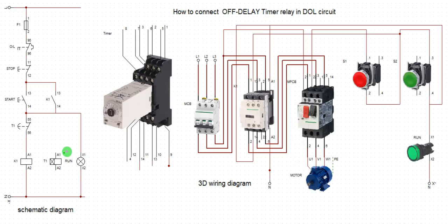All right, just pay attention, please. This is the coil, this is the contact. So I feed the coil through my latching branch and also feed the negative, positive, neutral from here. Within my latching retainer branch circuit, that is where I feed my timer. So that once this one is closed and here is latched, this one gets energized, I will have signal here. This signal will supply this. So once this one elapses, it will cut off. On this one closing, the entire system will shut down.